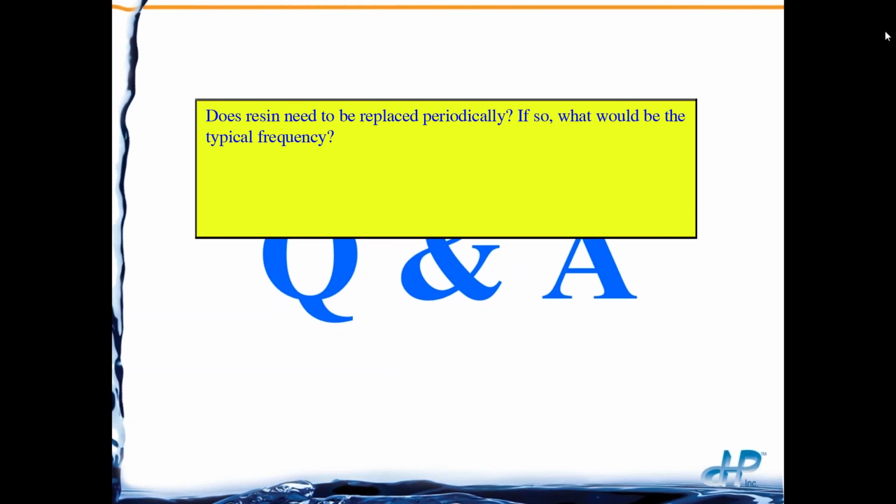And again, it always depends, and I mentioned EDI being used as an instrument that detects problems in your pre-treatment. But if your pre-treatment is working, and even if we do get variations in TDS or silica, as we showed in some of those slides, the EDI is typically working, and the pre-treatment is designed well. There are EDIs out there that I know of that have worked for quite some time, longer than 6 years.